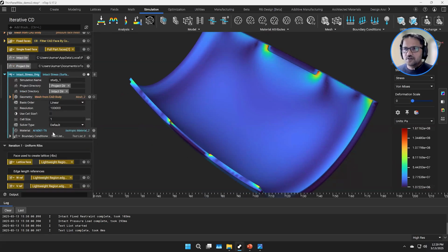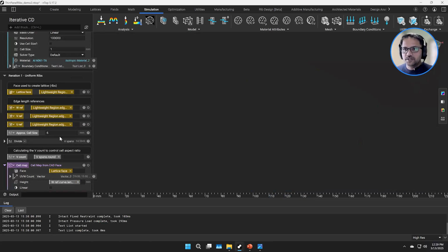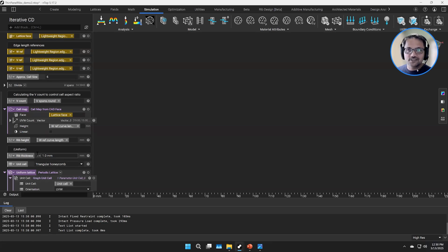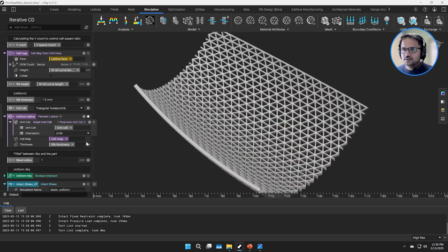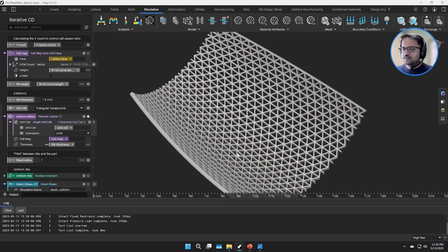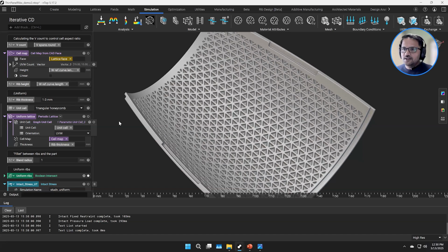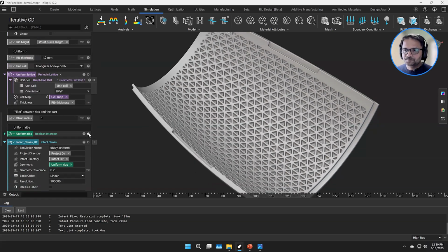All right, so now we want to start lightweighting it, right? So we go through the awesome capability of generating these ribbing structures. So these are the details of it, but at high level, we are using a triangular honeycomb lattice ribbing structure with a rib thickness of 1 millimeter. So this is what the uniform thickness ribs look like. And thanks to the magic of implicits, you can nicely combine the two into this new structure, which should be lightweight without too much loss in performance.